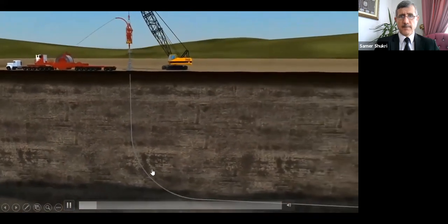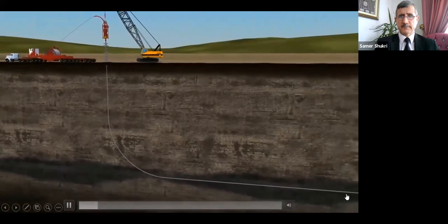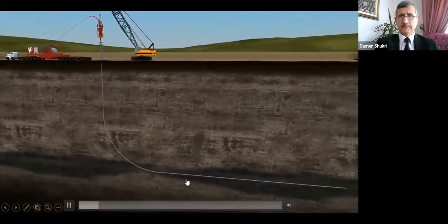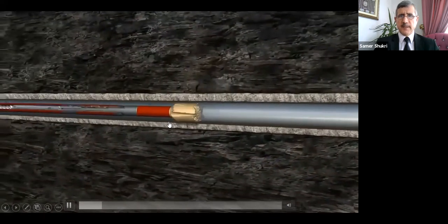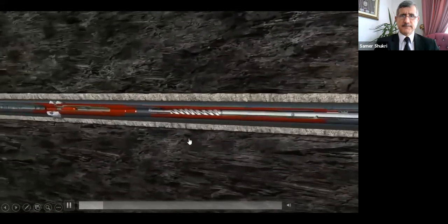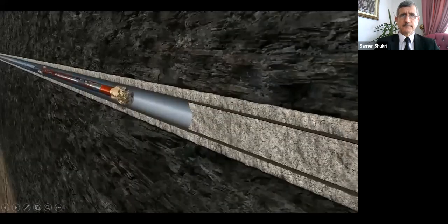One with a milling assembly to prepare the toe and clean up any residual cement, and a second with tubing conveyed perforating guns to perforate the toe. This is a horizontal well. Weatherford's Flowmax perforator allows this operation to be done in a single trip through the use of a flow-controlled valve, saving operators up to 30%.